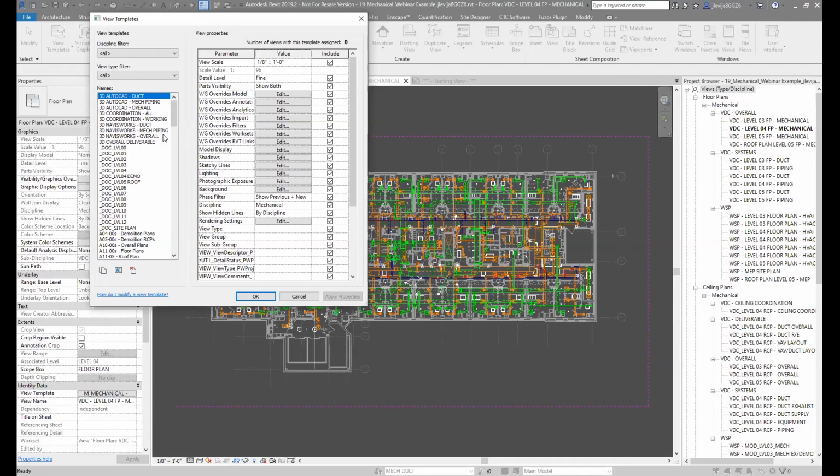So you should have a PDF file of what was in their model, just to make sure if you have to look back at something, you can. If you're looking for information on what fixtures need to be in a water closet at what height and stuff like that, depending on who's doing the setup there, you can go back to those P drawings, or those M drawings or whatever, and you can actually see what's needed there.